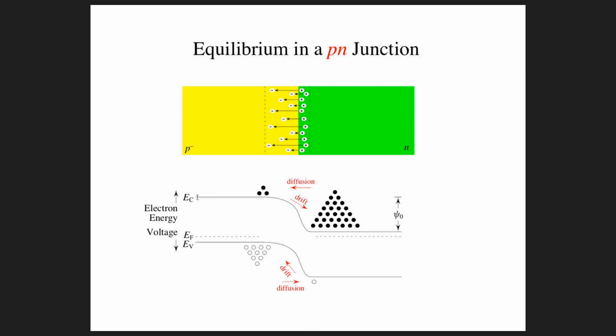So here is the conduction band edge. This is the lower edge of a band of energies in which the mobile carriers, the mobile electrons, the conduction electrons can live. And here is the valence band of energies, which is the range of energies that electrons that are in covalent bonds in the crystal, gluing it together, can live. And it's also the energy levels where the holes live. So over here we have lots of electrons in this n-type region. The concentration is basically n sub d. Concentration of holes over here is relatively high, not as high as the concentration of electrons. Concentration of holes over here is basically n sub a.